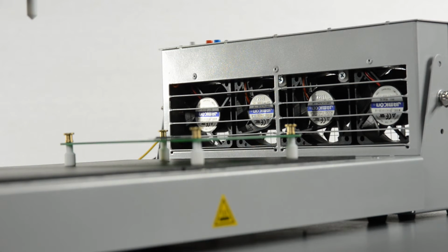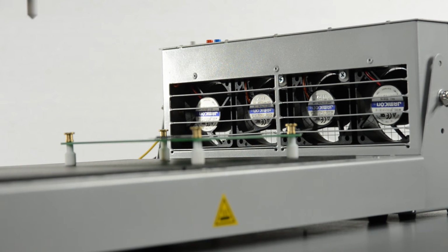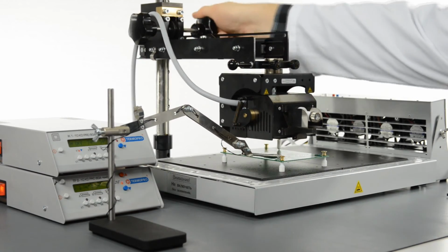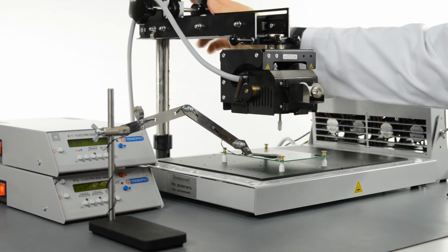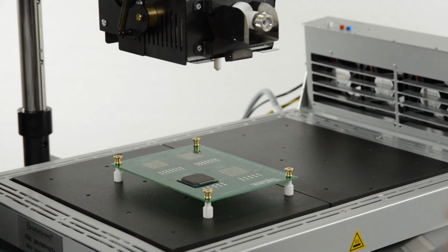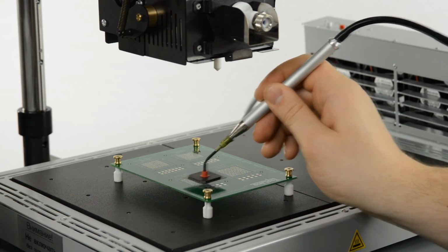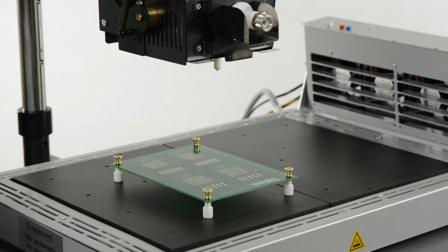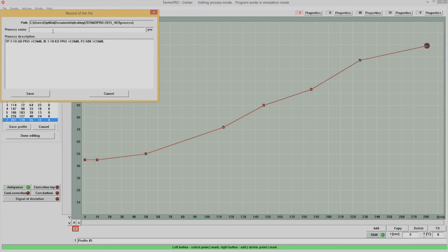In case forced ventilation is required, the air cooler unit IK650 can be engaged at this stage, and the program will recommend that the operator raise the top heater from the working zone. The process can be stopped at any stage by pressing the End Process button. If you run component desoldering, remove the component at this stage from the board by the method taken at your enterprise. After the process stops, the program will recommend saving the results into a file in the results directory. However, if you ignore it, the program will save the result to memory button number 1 anyway.